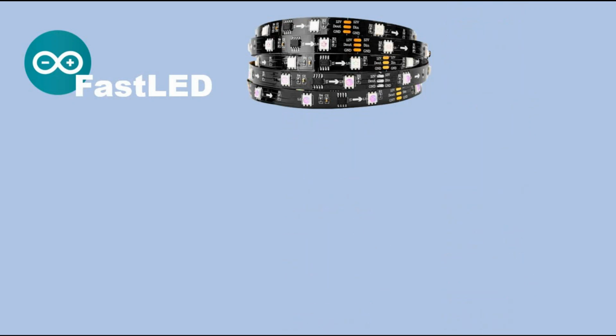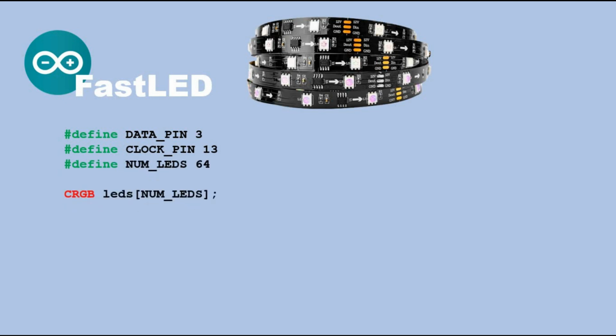You declare a number of attributes of the LED strip first, like the data pin, through which we control the state of all the LEDs in the strip. For certain LED strips, you also need to declare the clock pin. Then you need to specify how many LEDs your strip consists of. You also need to declare a table of CRGB type objects. The size of the table is equal to the number of LEDs in the strip, and each cell of that table contains 3 bytes representing the RGB values of the corresponding LED. Then we declare the LED strip and link it to the table we just created.